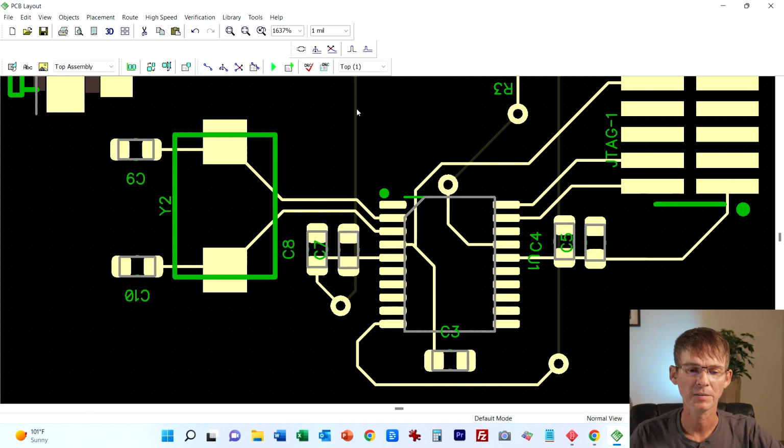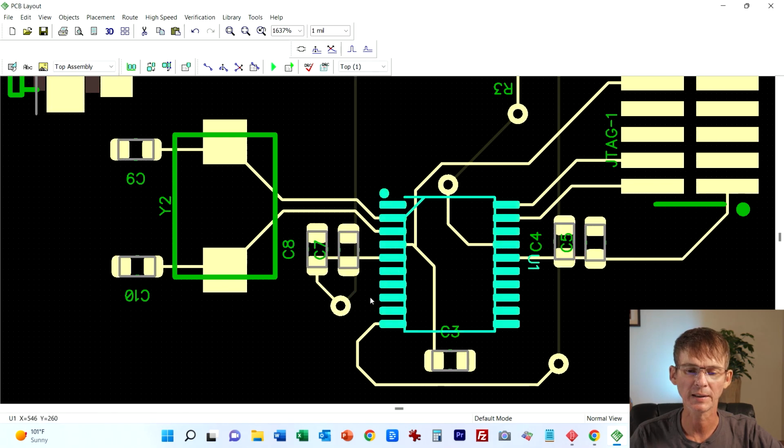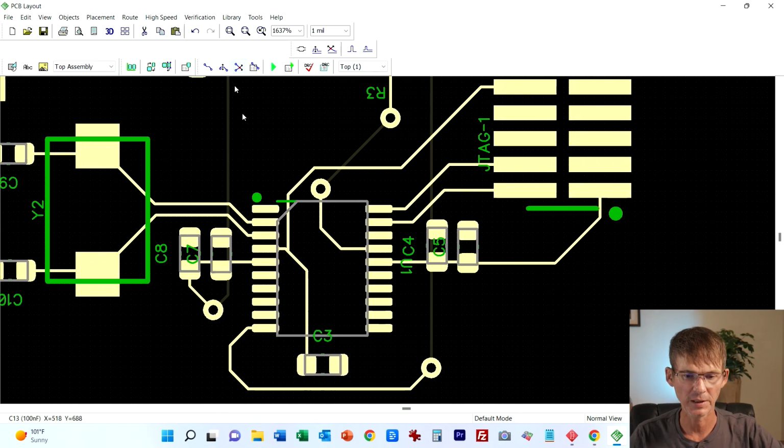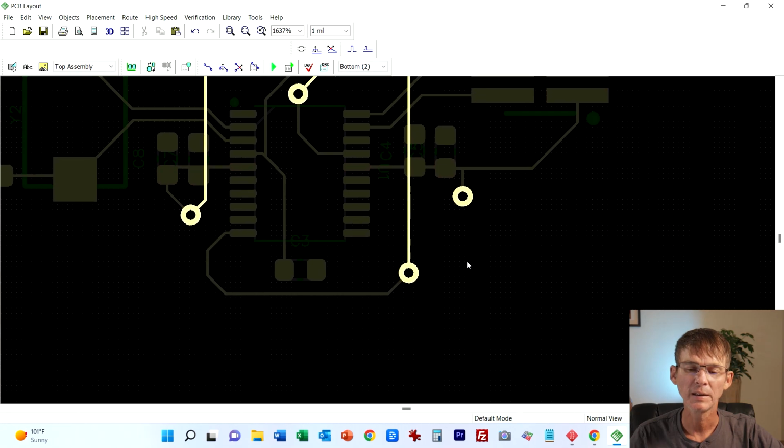This one power supply line of the microcontroller got connected up to everything else. We still have this line over here. So I'm going to add another static via. I'm just going to click it there. Actually, let's do about here, just so the supply goes ideally through the decoupling capacitors before the pin. So I'll just connect up here. And now let me go to the bottom side, and I need to connect this over to here now.